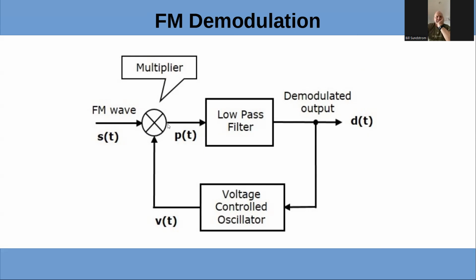So if the error signal is telling you that the oscillator is lower frequency than the reference, the error signal is going to increase the frequency of the oscillator until that error signal goes essentially to zero. And at that point, we call it phase locked.